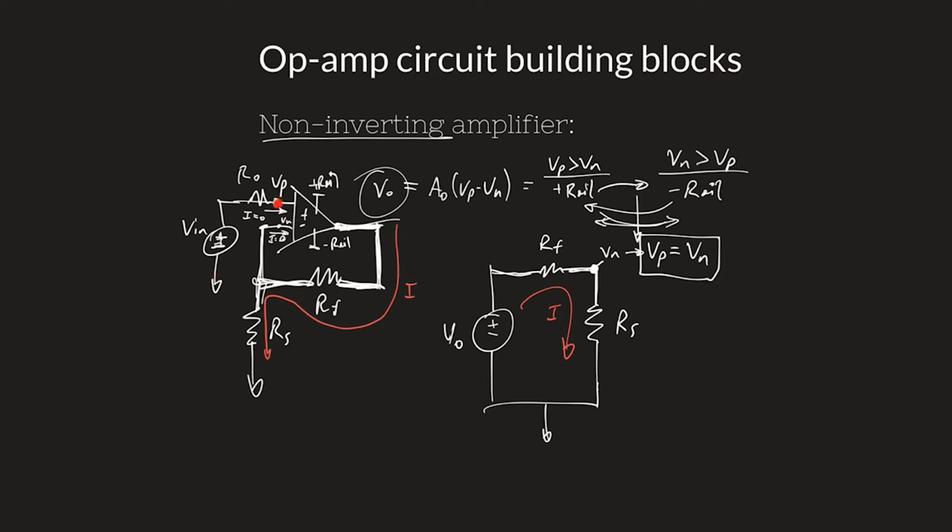That's the definition of a node voltage. So anytime you're looking at a circuit and somebody puts a probe somewhere and says, what's the voltage here? It means here with respect to ground. Here with respect to ground. Whichever, these are all the same common ground. So all these voltages are all with respect to ground. Vn is with respect to ground.